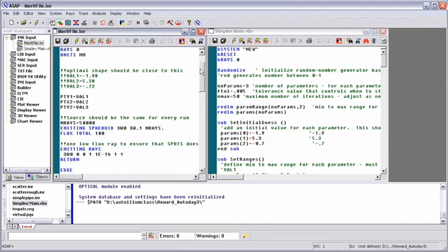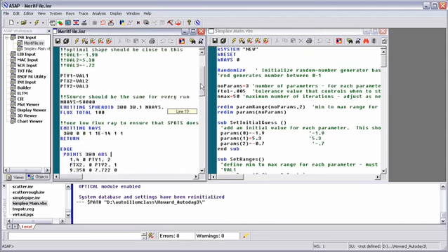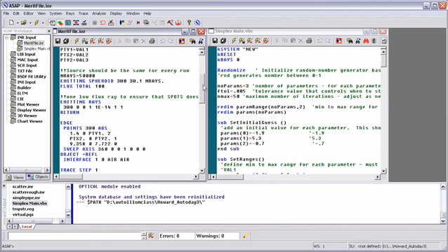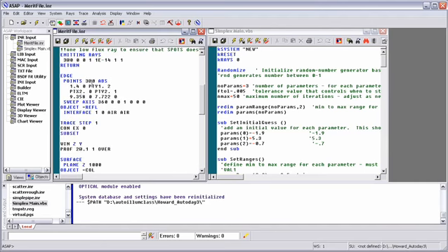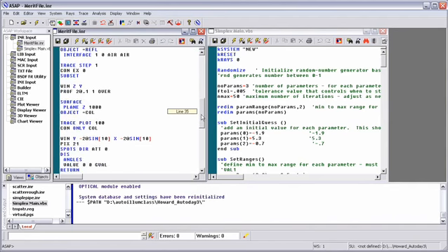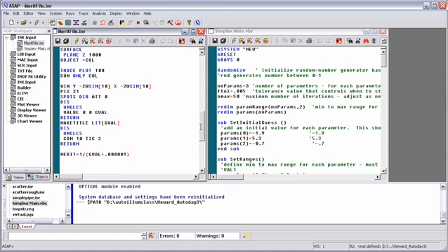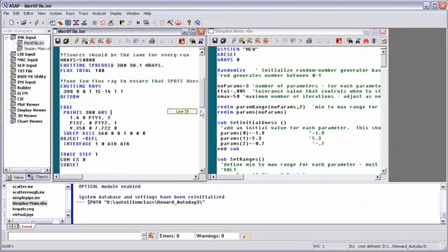So very quickly, what we have in front of us in our ASAP script file is simply a source, and then we're going to build some geometry. And what we've done is we've put in some variables for the points that describe this curve, and then this curve is going to be swept into a reflector. We're going to trace that reflector, and then we'll have a merit value calculated at the bottom. In this case, we're simply going to use the center intensity as the quantity that we want to optimize.